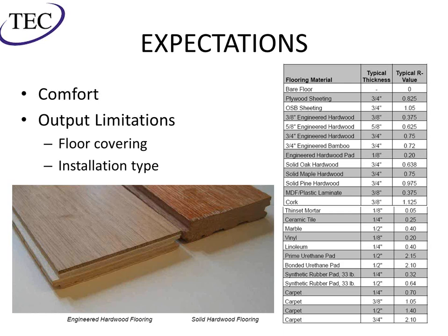And most radiant companies have all this tabulated. This is showing the R values. As I mentioned before, you have to insulate 5 times that on the bottom side. Most of this is tabulated, but you're going to want to check this with the actual flooring that you're using on the job to make sure that it matches. A lot of them, as you can see in this picture, engineered hardwood can take a higher heat and has a lower R value. So a lot of the newer products are actually beneficial to a radiant system.